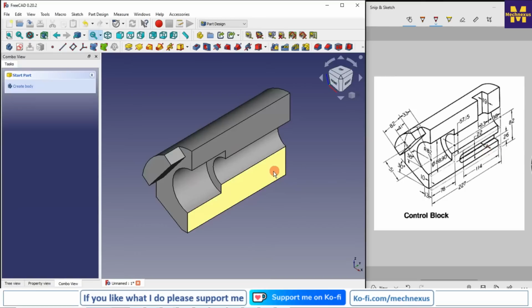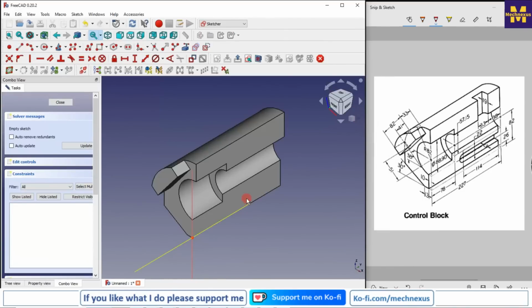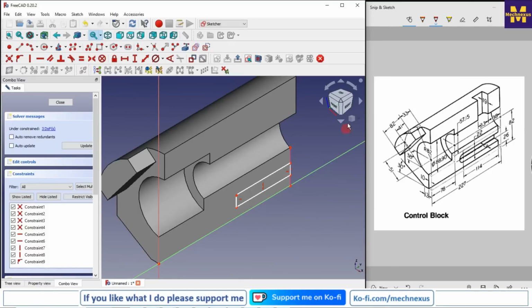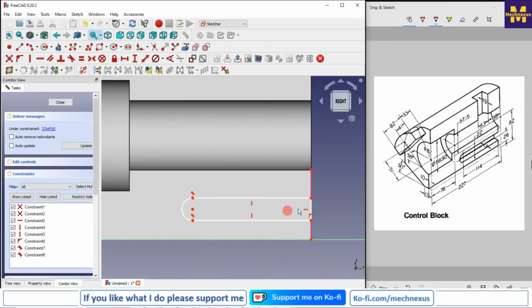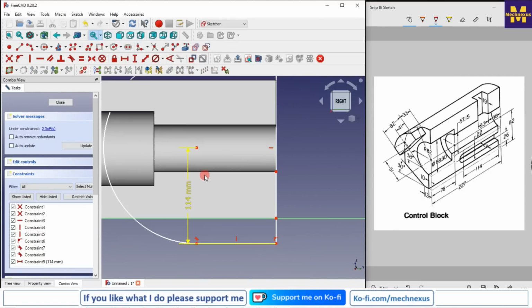Okay, and now we will make this slot cut here. So I will select this one and I will say sketch, and I will switch to the isometric, and I will project my outer edge and I will select rectangle. I will delete this line and I will draw the 3-point arc, and I will say tangent, tangent, and I will find the center, which is 114. So I will select these 2 points and give my dimension 114. Sorry, it is not this dimension.